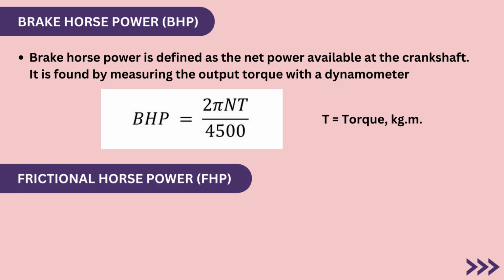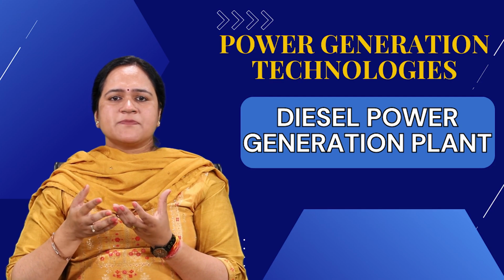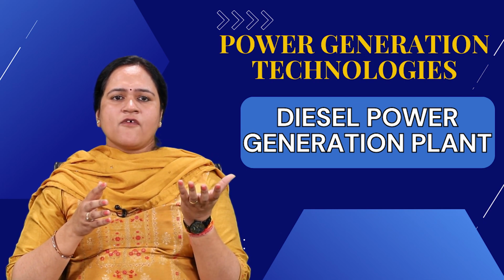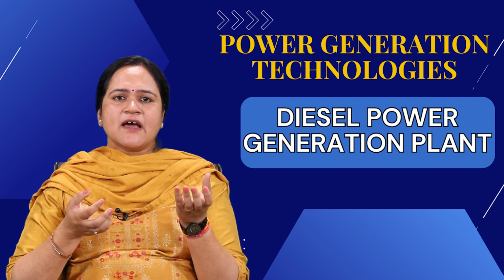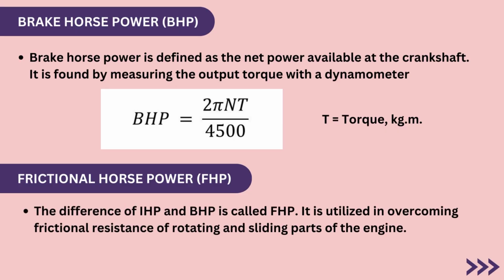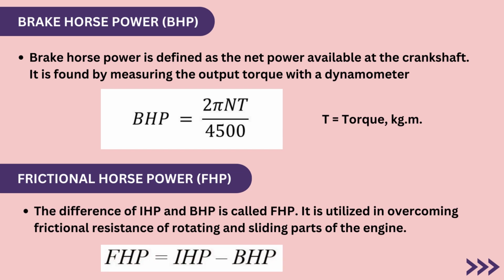Then comes the frictional horsepower. Frictional horsepower is the horsepower that is lost. Indicated horsepower is the indication of the power that should be available. Brake horsepower is the net power that we are getting. So frictional horsepower is the difference between the indicated horsepower and brake horsepower. So generally whatever is lost due to the friction is known as frictional horsepower, and it is utilized in overcoming frictional resistance of rotating and sliding parts of the engine. So frictional horsepower is equal to indicated horsepower minus brake horsepower.